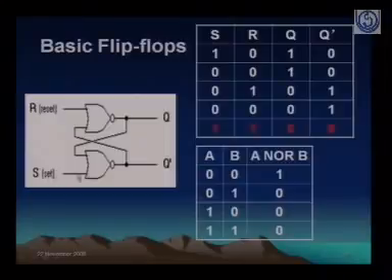Because one of the inputs is 1, automatically this Q prime is going to result in 0, as per the truth table over here. At the same time, what you see here, this particular output, the Q prime output, is now 0. And what is the reset value at this point of time? It is shown over here, it is 0. So after the propagation delay, what is the value of Q prime? It has to be 0 because from the NOR gate it got converted to 0, right?